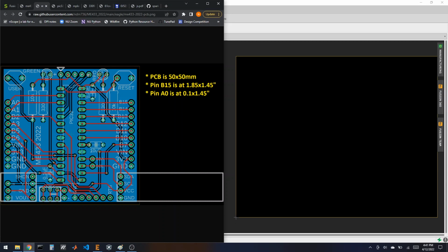Then we've got header pins for the SNAP and header pins for the USB to UART. We'll put those on the side, and we'll actually solder right angle header pins in. So the SNAP will come in from the side, not from the top, and the USB to UART will come in from the side, not from the top. And then here's our slide switch and our battery connector for power and the voltage regulator down here. So we're not really required to put any of those in specific places, so maybe I'll play around with that as we go.